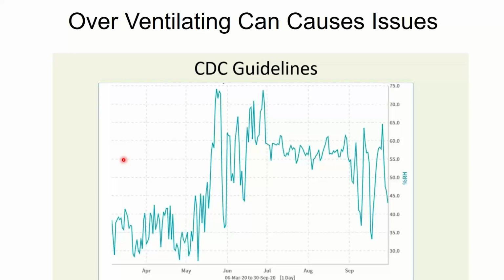Because for some reason in those thermostats, they only have even number set points allowed. So my choices are 54 or 56. So I just set them for 54. They float up to 59. They run the dehum mode, get me back down to 54, float up to 59, run the dehum, and so on. Keeping people comfortable is important.